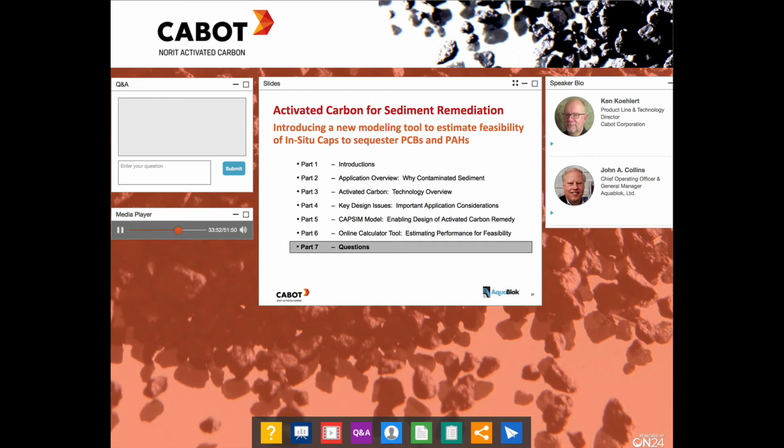Although if you give the activated carbon a chance, if there are low flow time periods of say 3 months, 6 months during a calendar year where that activated carbon can become reasonably well mixed with the underlying sediments, then those materials can stay in place even in a river or a flow situation for a long period of time. And I know that some of that testing was done up on the Grass River with some of the original activated carbon that was placed up there.